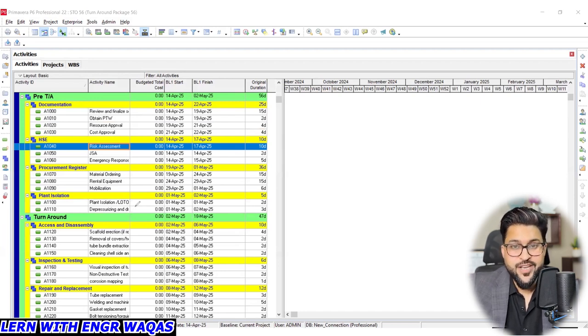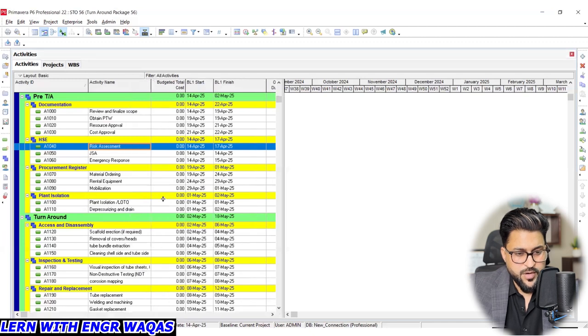So we need to take care when it is maintenance work. This is a very important thing: depressurizing. Then zero hydrocarbons should be there, because many lines are carrying high pressure and high temperature. So we need to depressurize and make sure that no hydrocarbons are there.